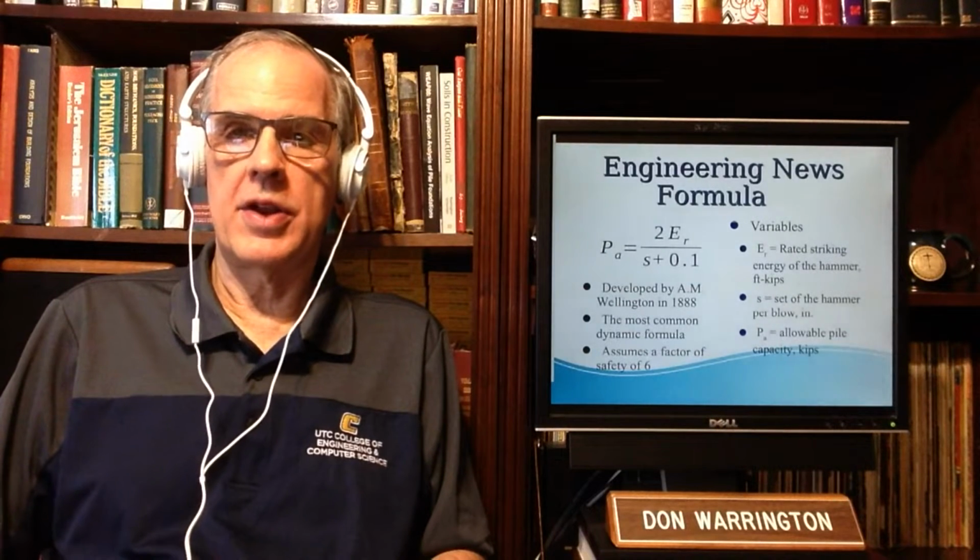What it basically said, however, again, as you see, is that there is an inverse relationship between the set of the hammer per blow in inches and the capacity for a given hammer energy. And hammer energy is another thing that is subject to discussion, but it's the rated energy for the ENR formula. The set, again, corresponds with our qualitative feel in the field. Our quantitative is a little more complicated than that.